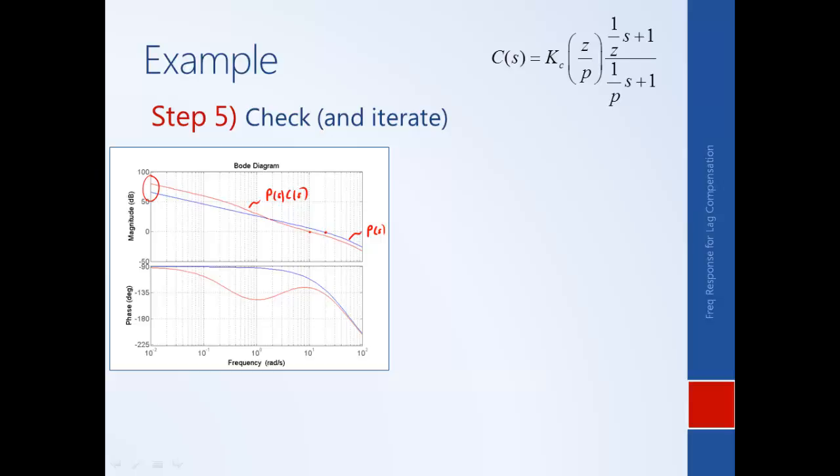And we've also placed the bump in our phase lag away from the crossover frequency. So this crossover frequency is at approximately 9.5 radians per second. We move the dip in phase lag about a decade below that, so that it doesn't hurt the phase margin too much. It has a little bit of an effect there, comparing it to the blue line, but not a ton.